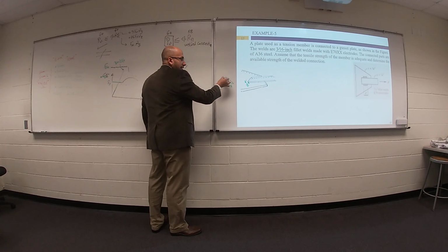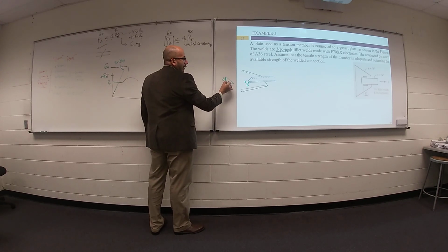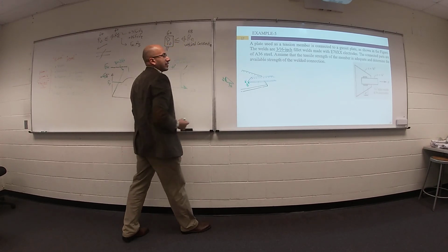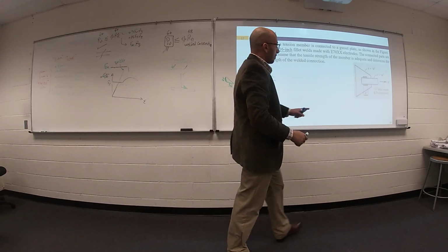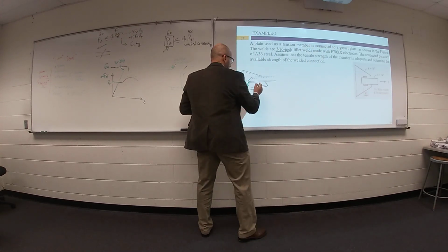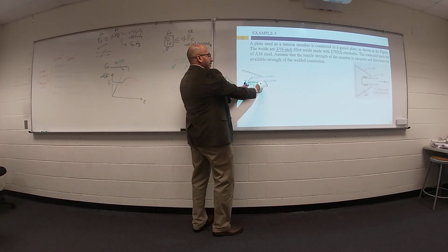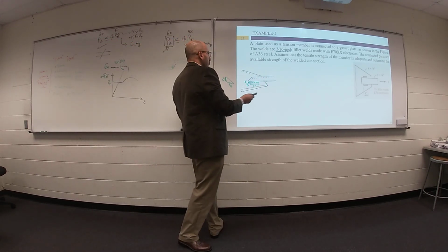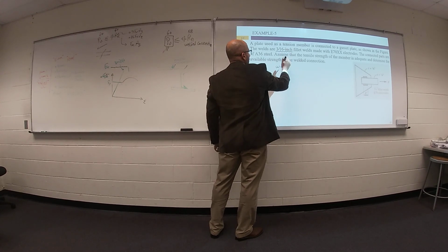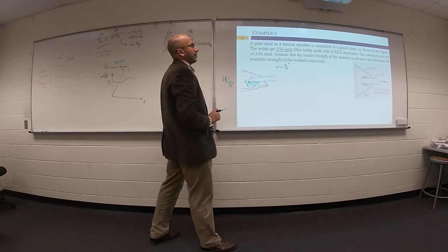This side is parallel to the vertical face of the thickness of your plate. This one will be parallel to the surface of the gusset plate. And this shape will extend with a length equal 4 inch only. Only 4 inch, from this side and from the other side also. So your W from this information equals 3/16 inch, which is called weld size.